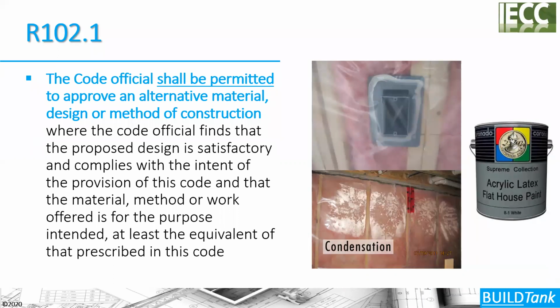There are a number of choices of vapor retarders, and some jurisdictions have completely amended out the requirement for a vapor retarder, especially a class 1 vapor retarder in our climate zones, and other jurisdictions are kind of defaulting to it. So from a building science perspective, we want assemblies that have the ability to dry.